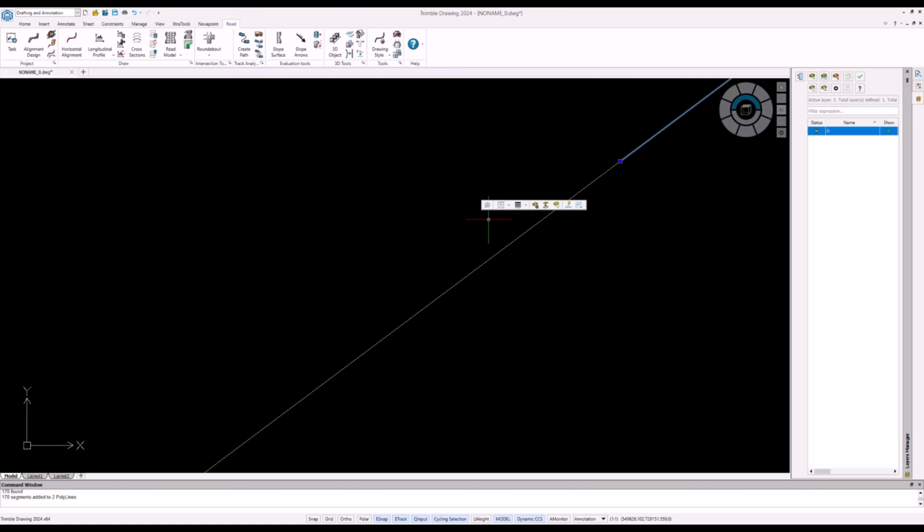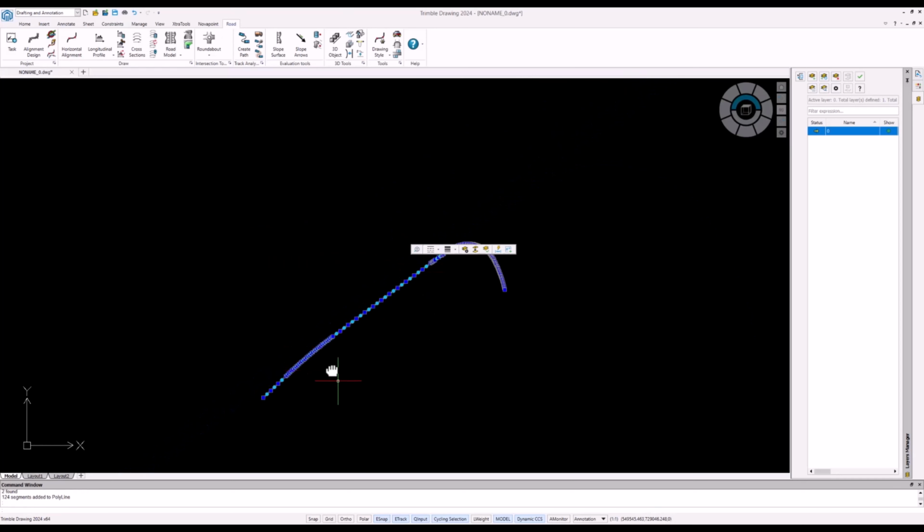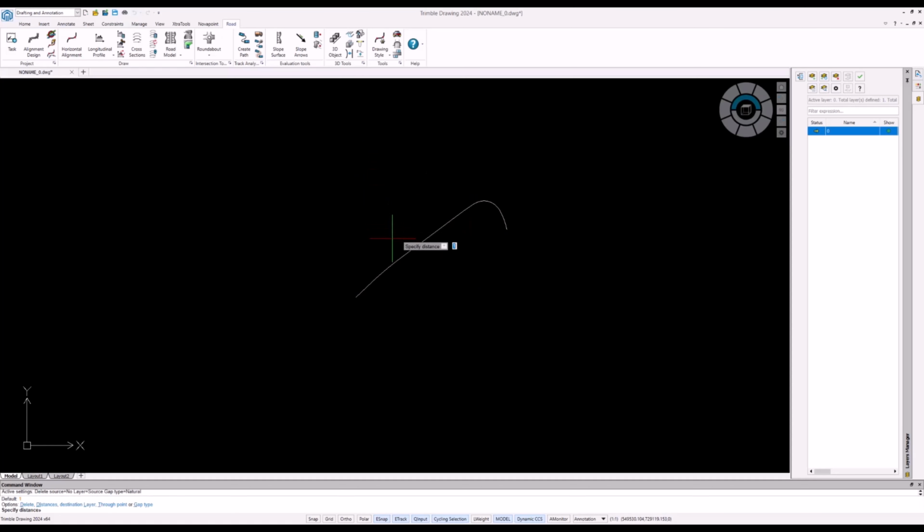I mean, there might be a slight discrepancy over here. Just drag the ends together and select and join again. Now I've got one continuous polyline that goes all the way across our main road and follows to the right. Now from this, we need to actually offset this by maybe, let's do 2 meters. So I need to go to offset, specify distance, I'll do 2. And my source entity will be this, and there we are. Now we're done.